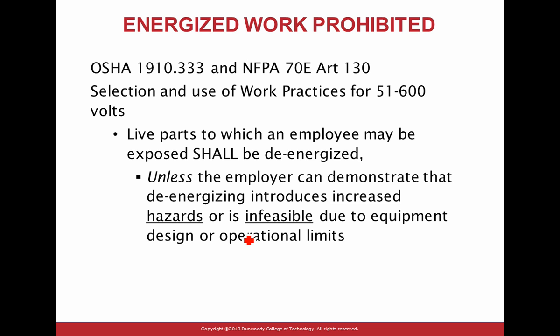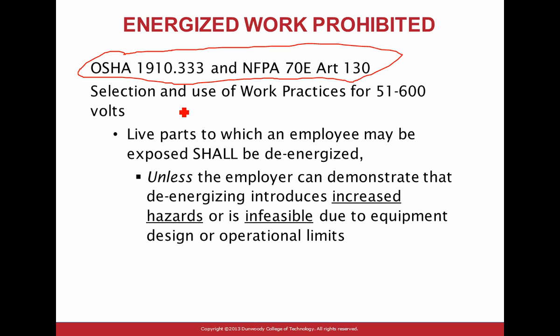So, energized work prohibited. We talked about this one, guys. This is the law of the land. Selection and use of voltages: live parts to which an employee may be exposed shall be de-energized. So if your employer asks you to work on it, these are your justification. These 2 articles at the top, NFPA and OSHA, tell me that if I work on things energized, they have to be de-energized.